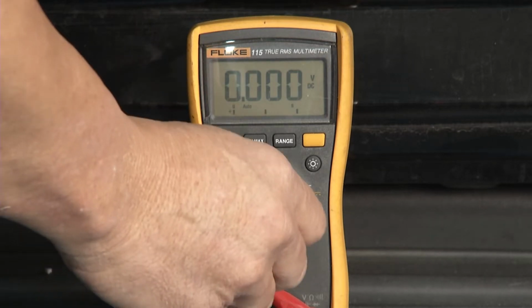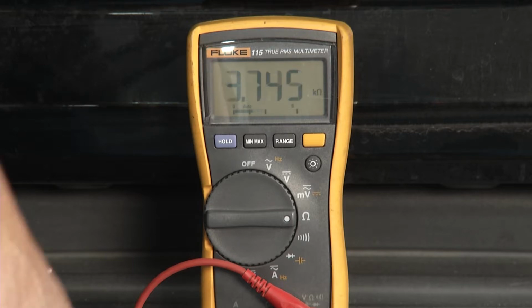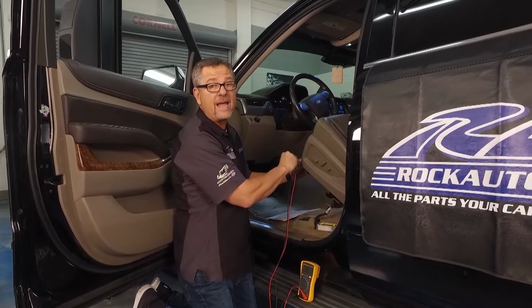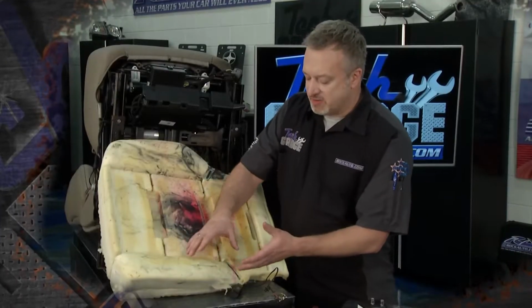I'm going to look for voltage, and it wants less than 1 volt. We're good there. And I want to go to ohms, and it says ohms need to be anywhere from 27 to 51, and we're OL. Well, the OL shows us we have a haptic motor problem, so we'll just get the seat out and take it over to the bench so you can see what's going on. You don't want to miss that.